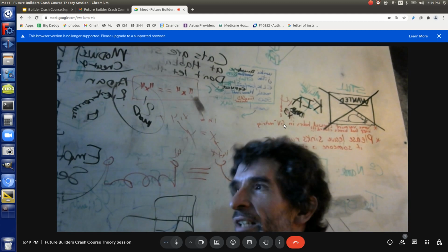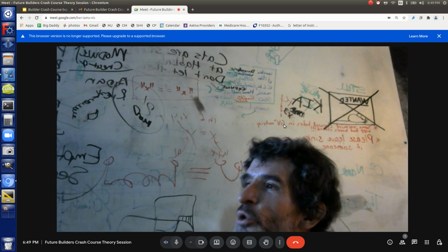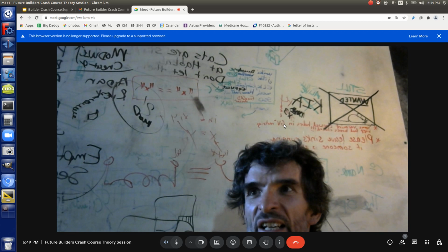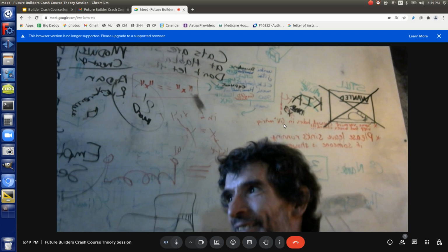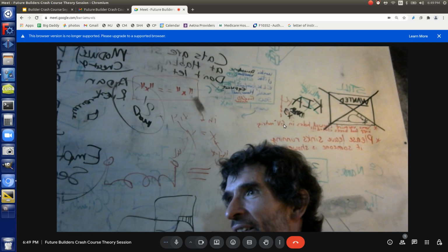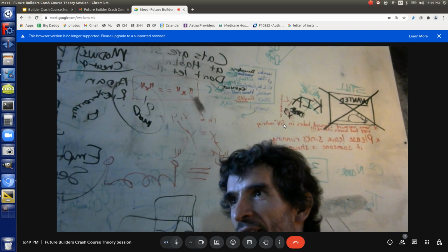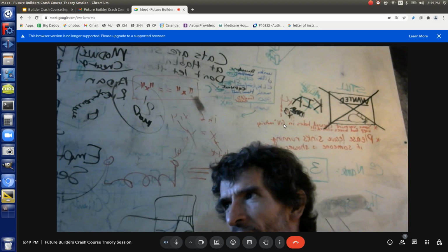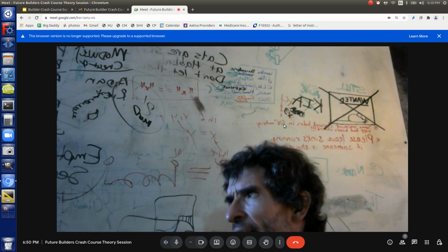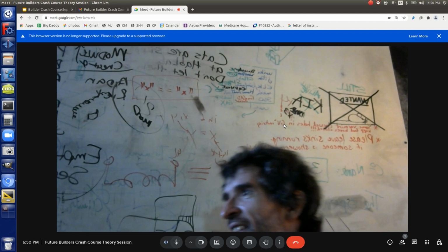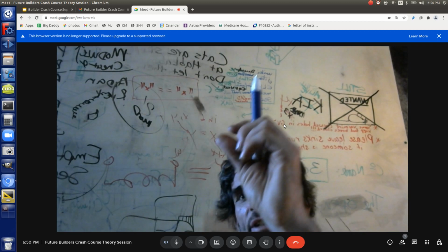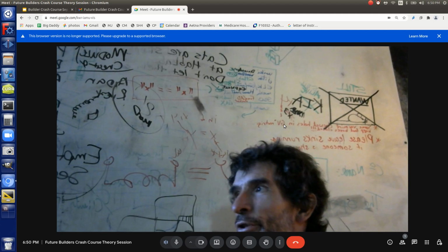Let's assume that nail is so long and so strong that the wood's not going to pull out, because the wood is like hedge, which is probably over 1,000 psi. It's almost like a rock. Osage orange, for example. Say you stuck this nail hard into this huge block of wood, and we say, okay, we're going to pull this with this nail. When's this nail going to break? That's an application of the tensile strength. So what's a typical nail? What's the diameter of a nail? It's 1/8 inch.